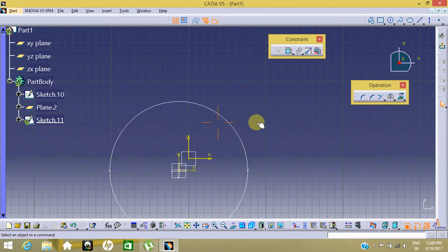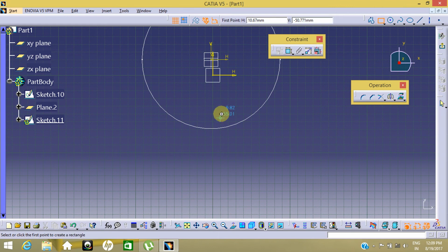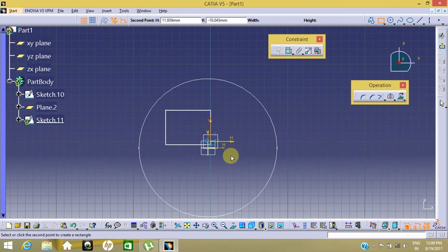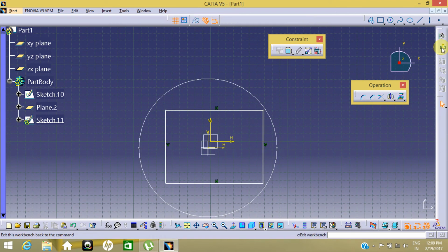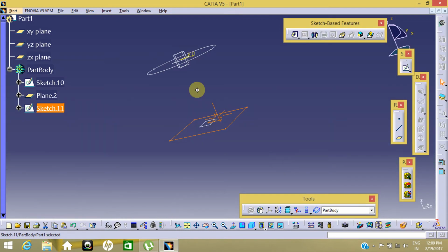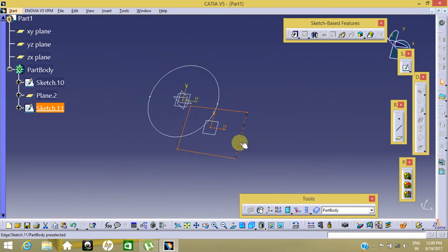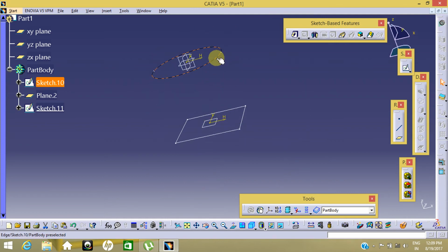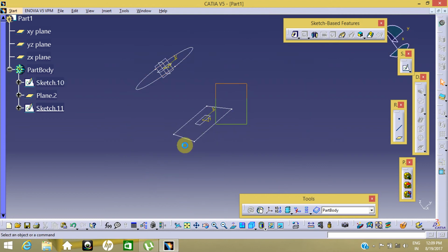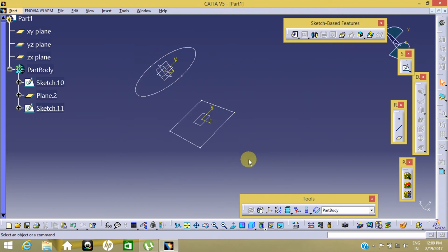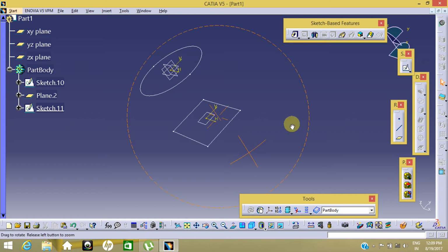So your sketch has been broken from this point to this point and you now have two sketches right here. Just again break this section into 2 equal. So now it's also been broken up. Now again I am going to break this section. So this has been almost 4 equal curves here.